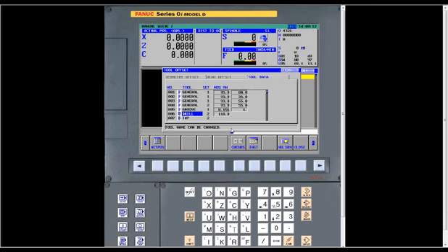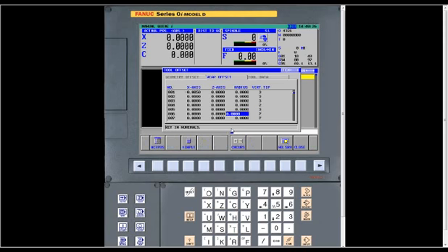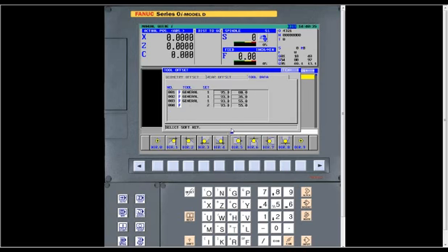Then for a drill, all it asks for is the orientation based on your type of machine, and then the angle on the drill. Then also one note for when you're doing this, on a drill, if you want it to show up in the simulation, you do have to put a radius value here, because then it will actually show that size drill. So it's important you put a value in there for a drill.